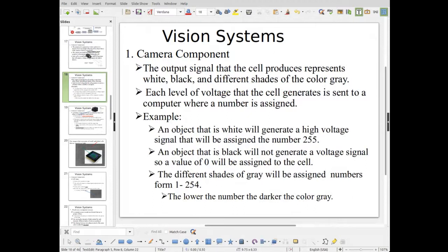So what happens is that light falls on them, and we get an intensity. Most of these are fed into an analog to digital converter, which is only an 8-bit converter, which means you can only see an intensity range between 0 and 255. 255 is as bright as you can detect, and 0 is black, no light.